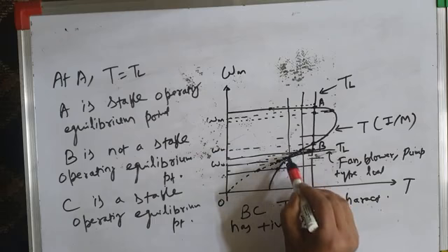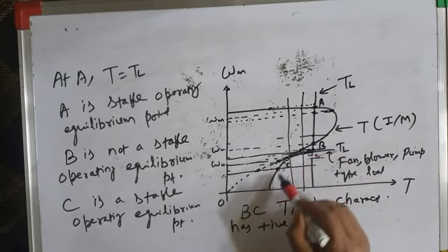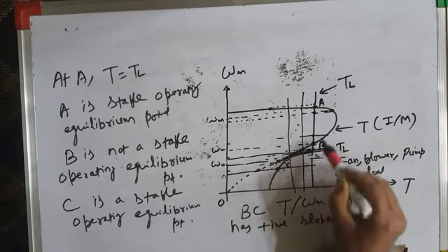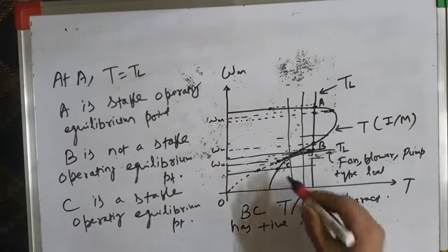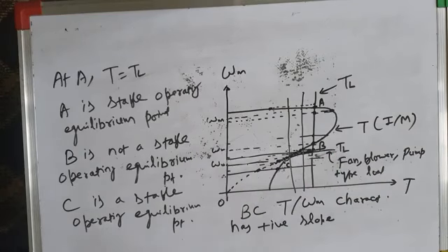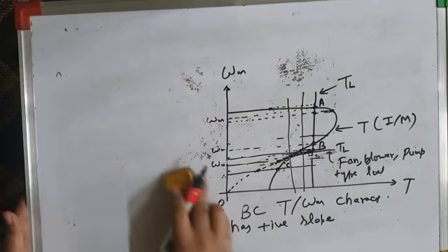It will be an unstable operating point all the way. So this type of characteristic, BC, or even from here to this B, is unstable, because the slope of the torque speed characteristic is positive, and whenever the motor torque speed characteristic has positive slope, most probably for most of the loads this is an unstable torque speed characteristic.